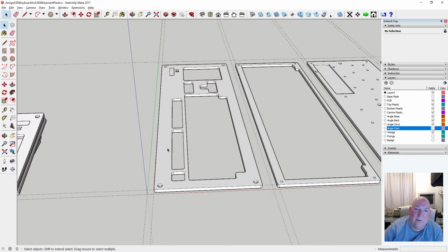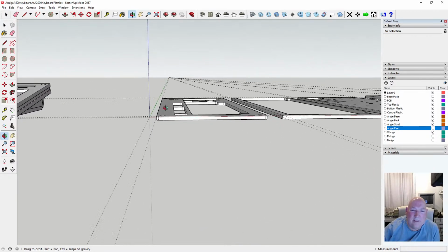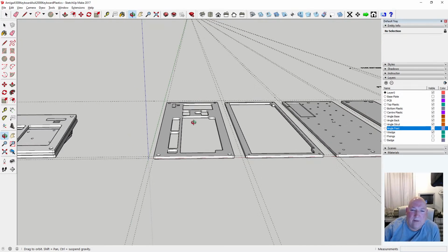You'd have to have a spoil board on there that's able to be screwed and drilled and tapped into. That reduces your height. I've got about 75mm height on the Z-axis, so the spindle can go up and down 75mm. The more spoil board you have on it, the less you can go up and down. You have to alter your spindle clamps and all sorts. You don't want to be messing around like that.